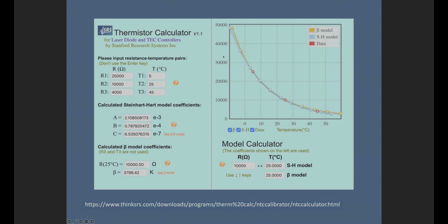Look at a spreadsheet. Many spreadsheets, like this one, have the calculations or the formulas. This is using A, B, C, and D. To get resistance, you use these coefficients. The coefficients are given to you. And for temperature, you use these coefficients. They're already given to you. So if you want to find temperature, you plug in for the particular thermistor, they have the coefficients right here. You plug those into this formula. If you're looking for resistance, you plug these into this equation.